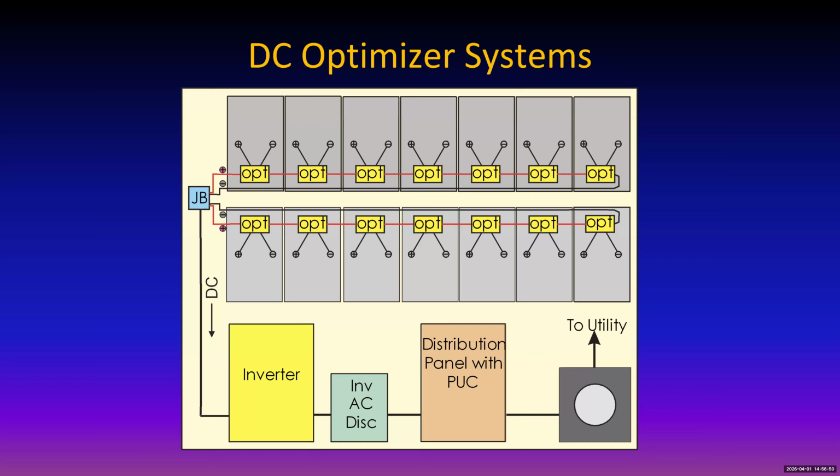And there's another thing that's called rapid shutdown. The optimizers are smart enough to know that if they get a signal from the inverter, they simply open the switch and there is no power output at all. It's all just run open circuit at the input to the optimizer.